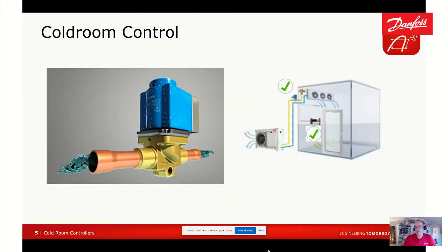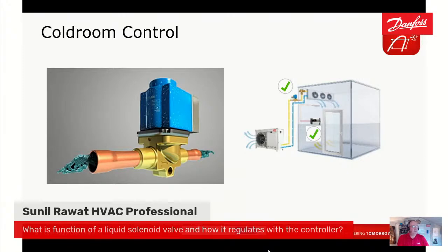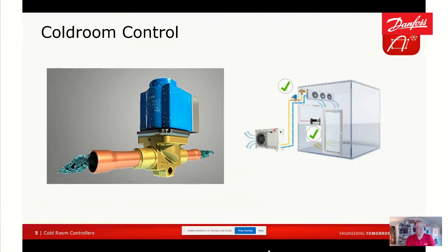So if we talk about solenoid valves, and this is the question from Sunil, what is a solenoid valve? Basically, it is, I would say, the preferred way to look after your refrigeration system. When your room is down to temperature, your controller, whatever that is, and we can look at the various options of that in a minute, the thermostat would say, okay, my cold room is cold enough, and it would drop the feed to the solenoid valve. That would start the system to pump down, and we would pump the liquid down into the receiver of that condensing unit. The system would go out on LP.